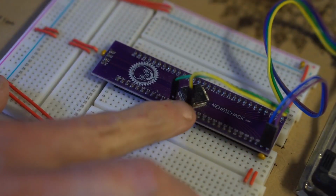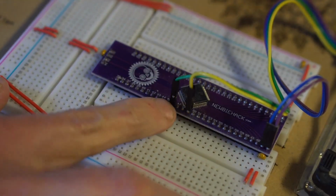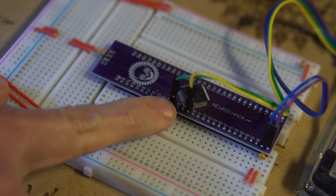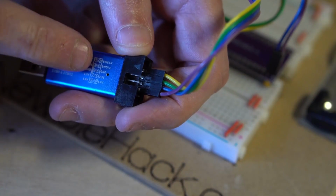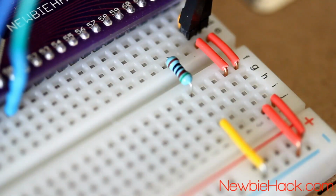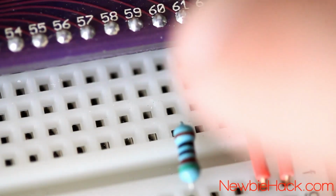The SWCLK, which is the clock, will be connected to this pin here, which is number 49, and number 46 is SWDIO, which is the IO pin. You can see those two pins here, SWCLK and SWDIO. And this diagram here corresponds to the pins in the back of the ST-Link. You can put a 510 ohm resistor going to ground on the BOOT0 pin, and that BOOT0 pin is pin number 60.